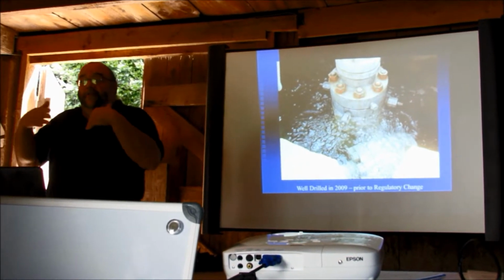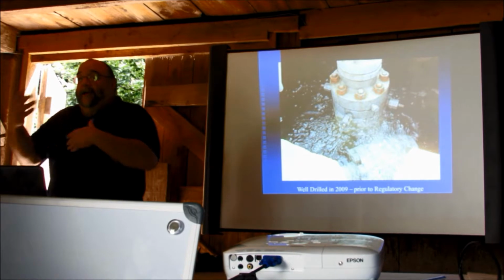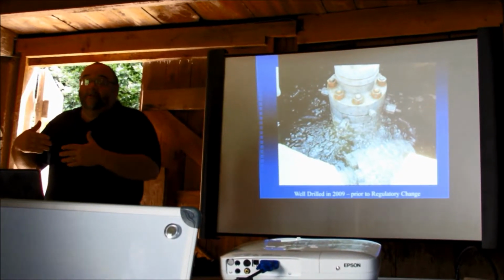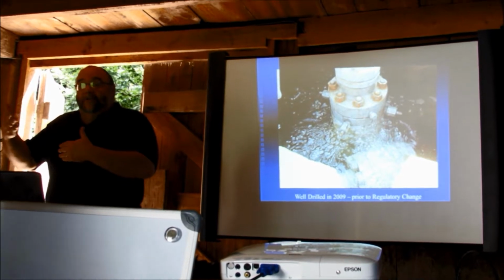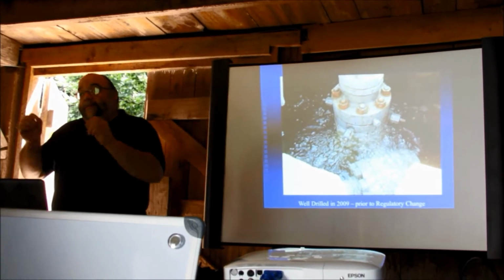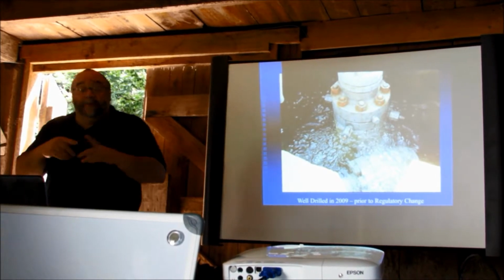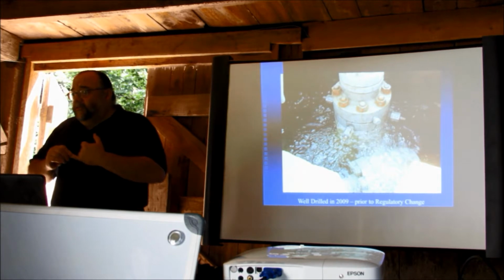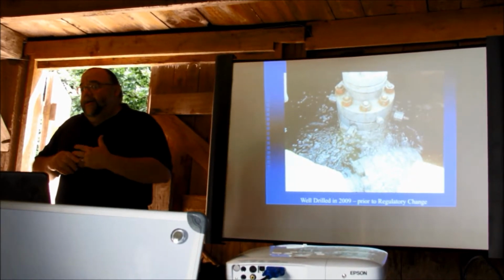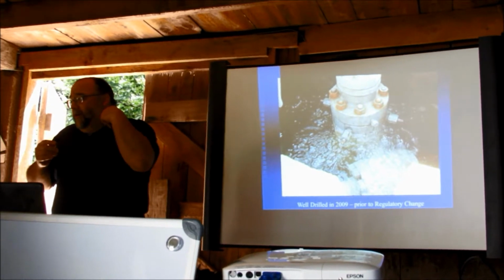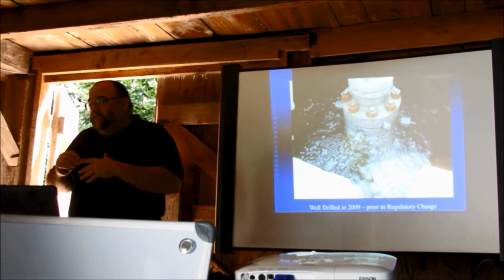If you get your baseline testing done, and then all of a sudden someone comes in and starts drilling or digging, even foundation work, and the water gets dirty after a rain or during drilling, it could be that. But keeping that log is important. Typically, what you'll see is a short-term issue. You pump the well and that goes away. Typically it'll be dirty water, iron, manganese, discolored water. Usually no methane signatures with that.